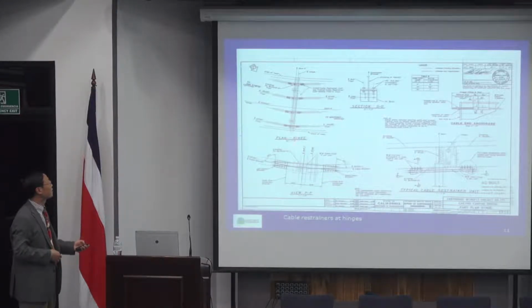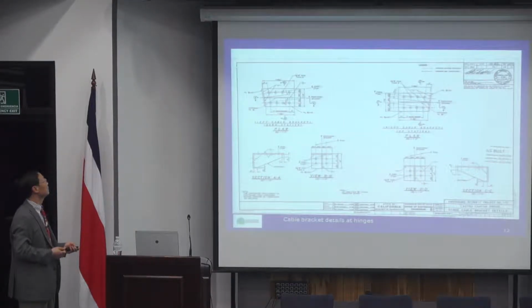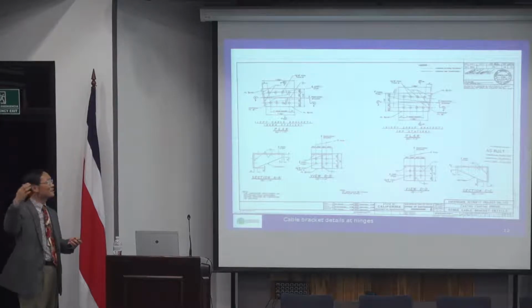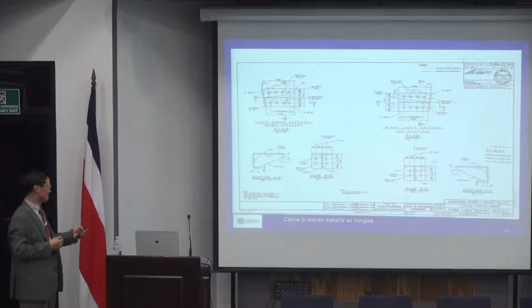Before, they only had a very weak connection, and now you introduce tension rods at the bottom. Once you introduce tension rods at the bottom, that will prevent the girder superstructure from moving that easily. Because once you move, that will introduce a force that will push it back to the original shape. Yeah, these are the very detailed parts. Again, whenever you introduce something to the existing structure, try to use a bolt connection. Don't weld anything to the existing structure.